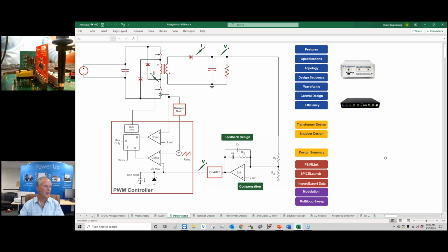Guys persisting on about the regulation between the windings, just say you have to come to the webinar for that. Where's the question? Down the bottom? Is there any hard rule for regulation winding multiple output transformer? No. Sorry. Is there a maximum number of outputs on a single transformer you have designed? Yes, it's determined by how many pins are on the bobbin. Sorry to be facetious here, but that's it. I've done 5 output transformers with forwards, 5 output transformers with flybacks, and you just run out of pins after a while, so you have to use a bigger bobbin.